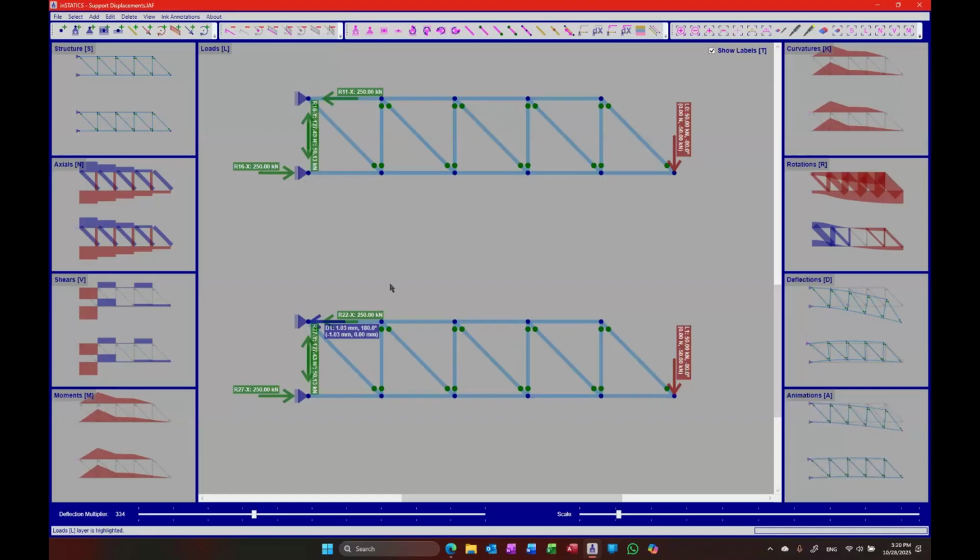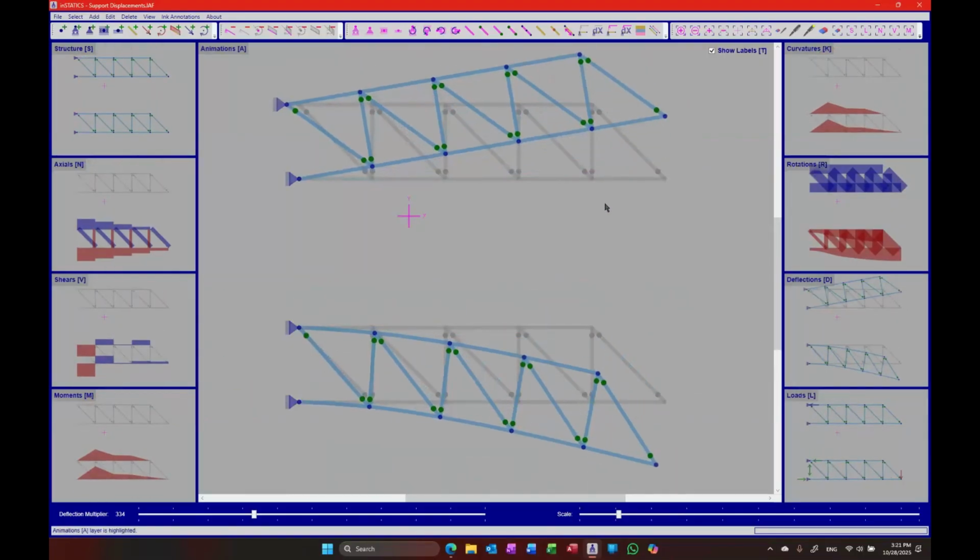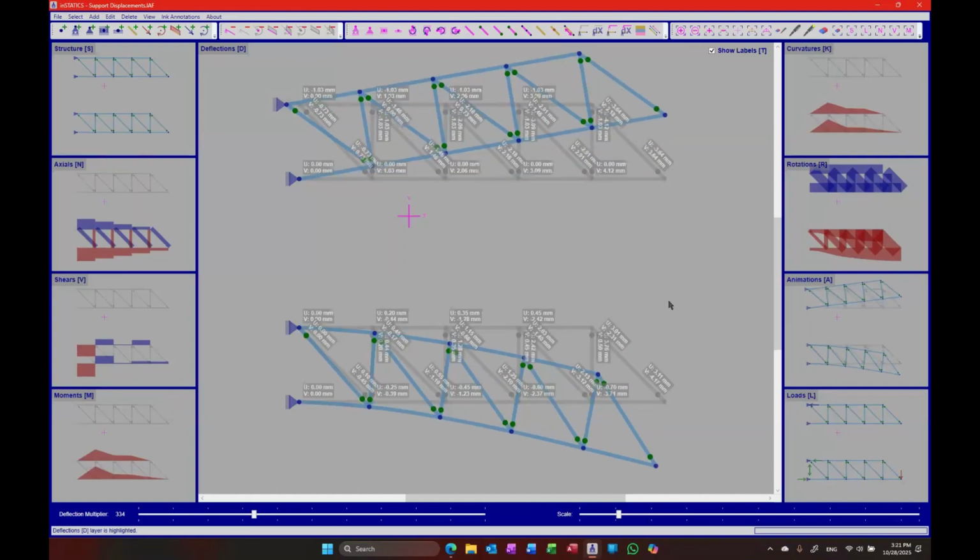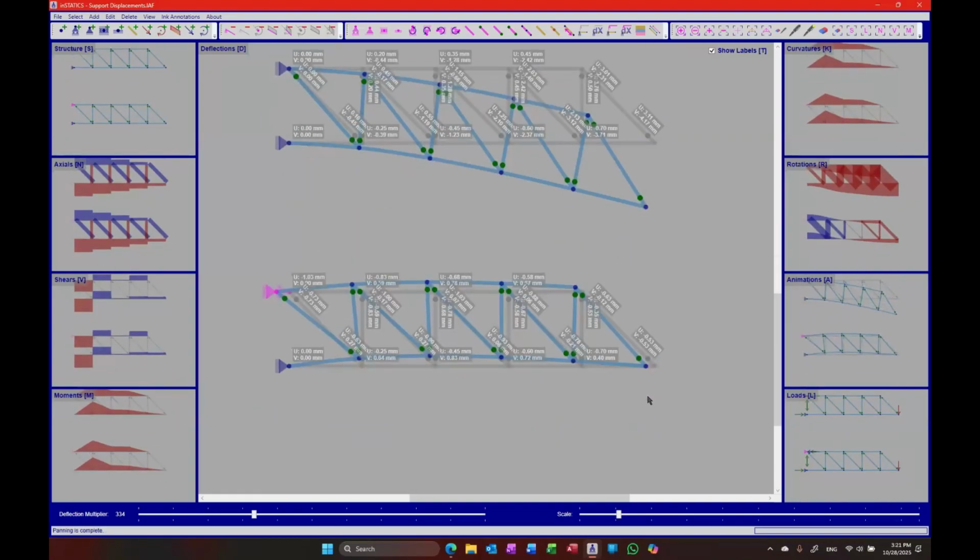So in a real world scenario, if you have a long cantilever and you know it's going to deform too much down, you can actually pull the top end or fabricate the top end short this much, so that you basically build it like this, and then after deformation, it becomes basically zero.